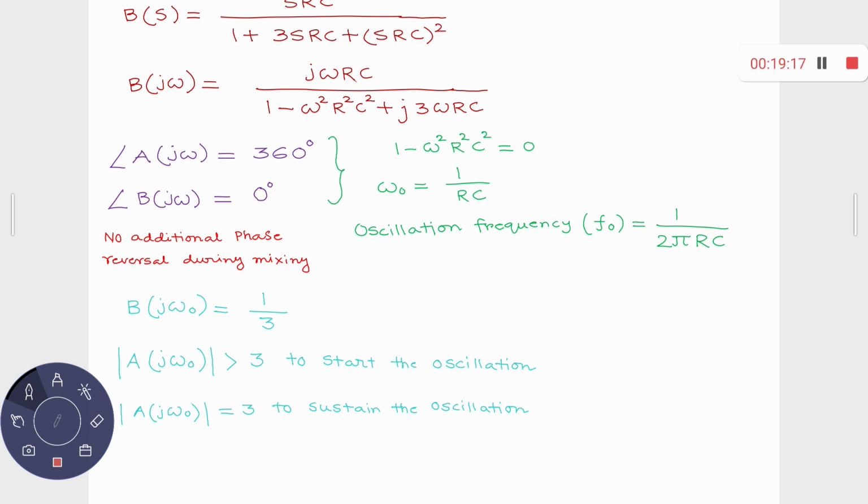Now at very high frequency, what happens? These resistors are not purely resistors. Apart from that, they can also exhibit some behavior of an inductor in series and a capacitor in parallel. Some parasitic effects you can expect at very high frequency. Therefore, for very high frequency, if you would like to generate a signal of a given frequency and ensure stable frequency generation, then people have opted for the LC oscillator, which involves inductor and capacitor.